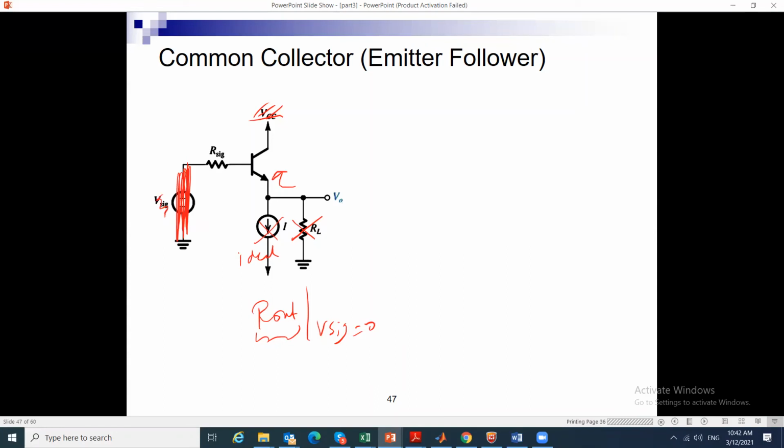Because in the sheet, it tells me that if I have RB, I can use the equation in a specific form. Here, without the complexities, automatically they tell you what it is as a function of Rpi. Okay, so you can use the equation that is derived here. So this is the only exception where it is easier for you to find Rout for this specific circuit from here. Okay, and we can go over it in practice later.